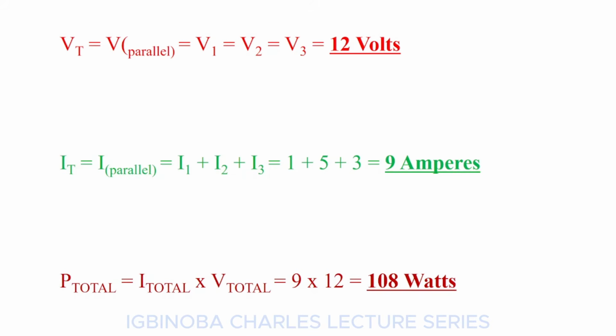So after calculating your current of the panel using the nominal value, it is very important to multiply it by 1.1 so that you will use that value in order to do your cable sizing.